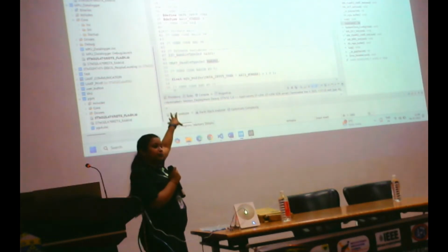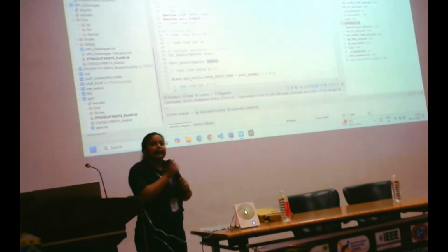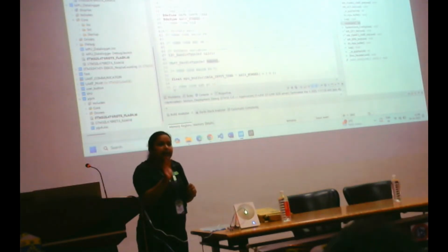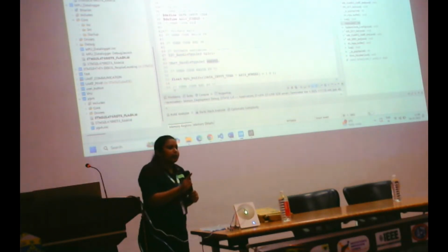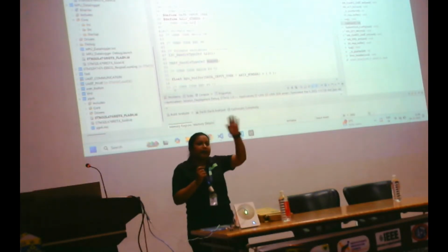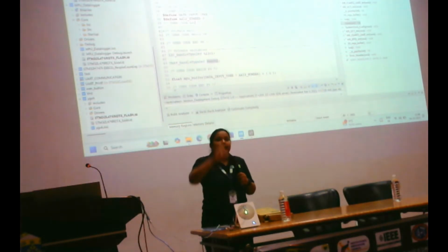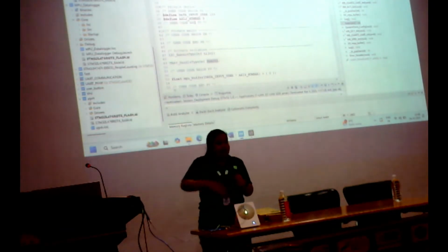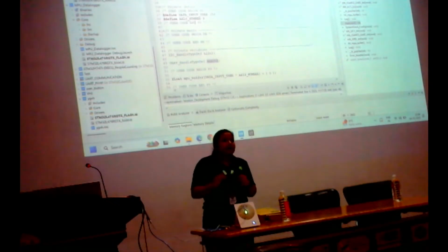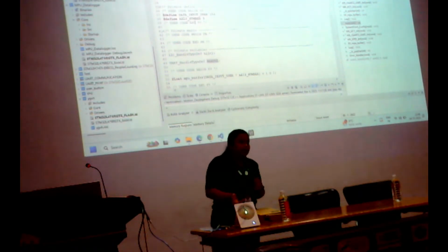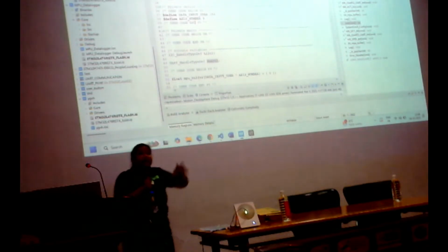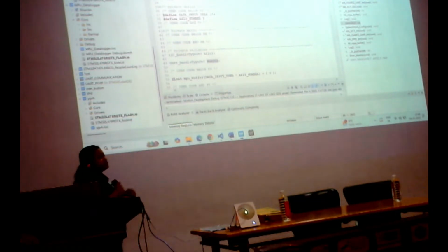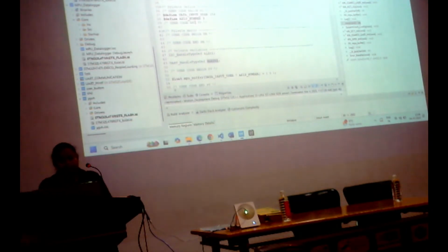Definitions I have to write in the definition part. Includes, I have to write in the includes part. If they write here and there, it will show an error, okay? But in Arduino IDE, you don't know where to write what. Students get confused. First input initialization, this function, printf statements, final logging part, all these things come. They get confused what to write after what. So here, they will give you a template. From there, you can just insert your code. So this is an advantage for the data logger code.